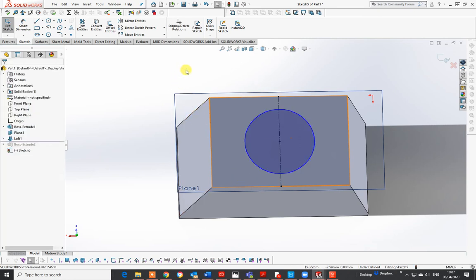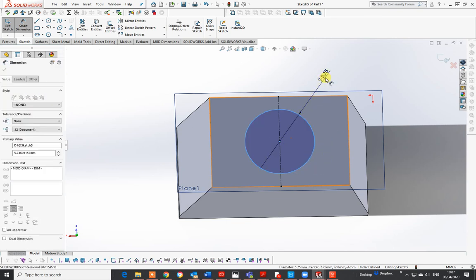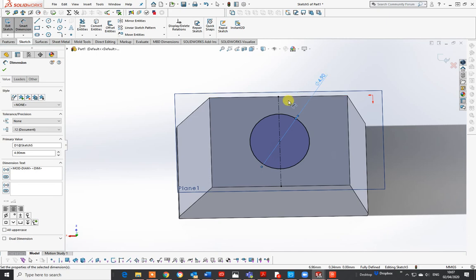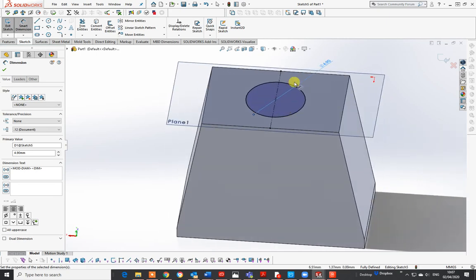Why? Okay, for those of you who have got onto this, I need to put a dimension in. So if you look at your drawings, smart dimension of that circle is 4.9. Type in 4.9. Now these are fairly odd dimensions because I've actually measured this off the original, and they are very, very precise Lego. So I've got that there.